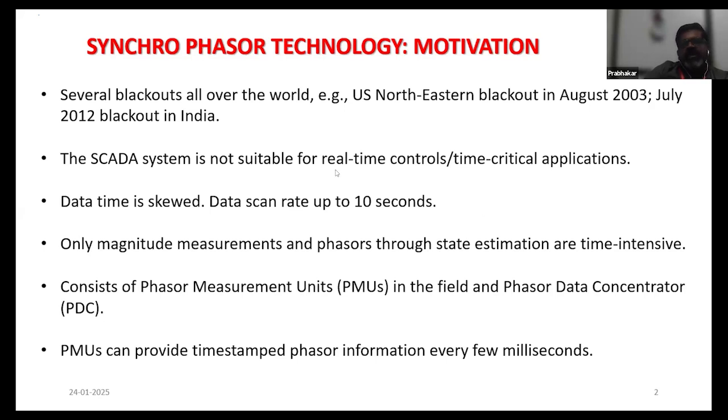And when it comes to real-time control and wide area networking, the SCADA system is not really suitable for a local generating station. If you want real-time monitoring, it's okay. But when it comes to real-time for a very big network, this SCADA system fails. And similarly, the rate at which data is available, somewhere around 40 or 50 frames per second, is possible with this technology.